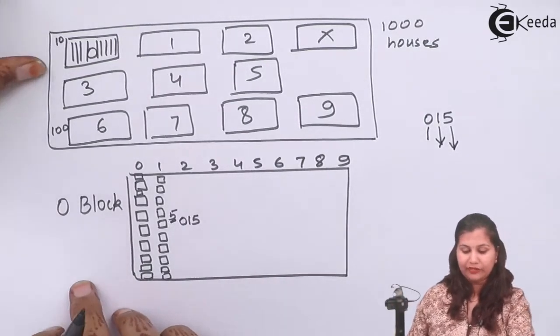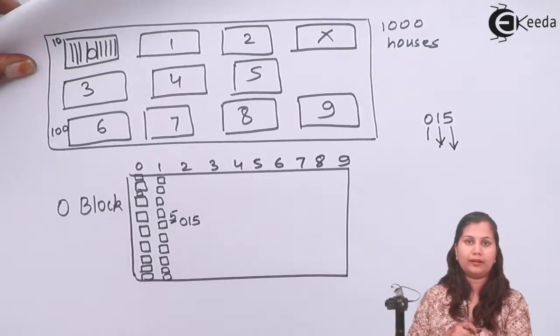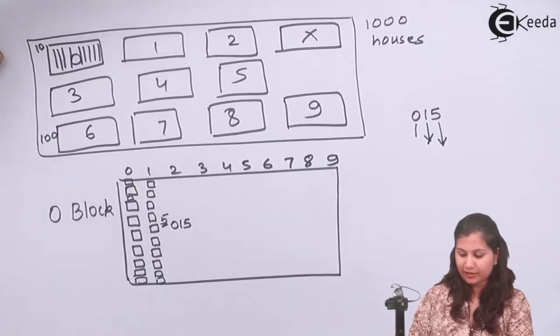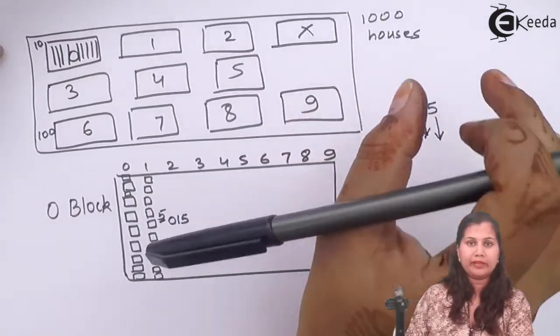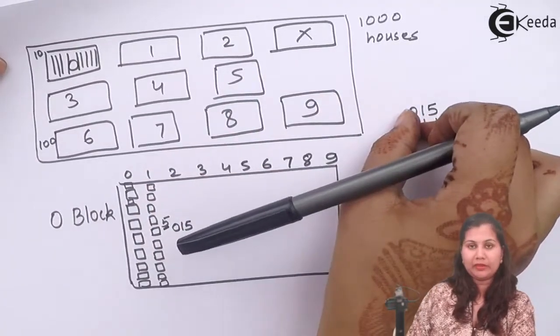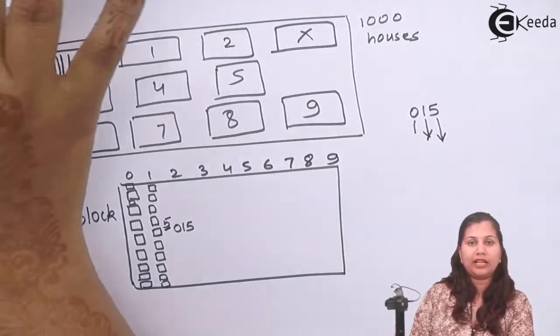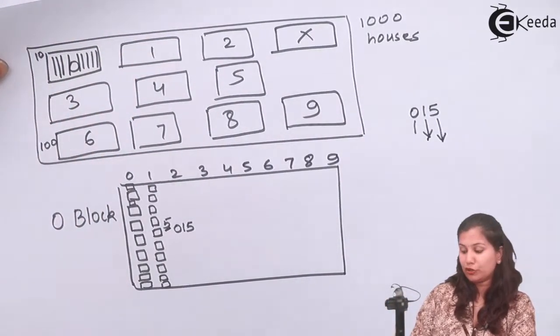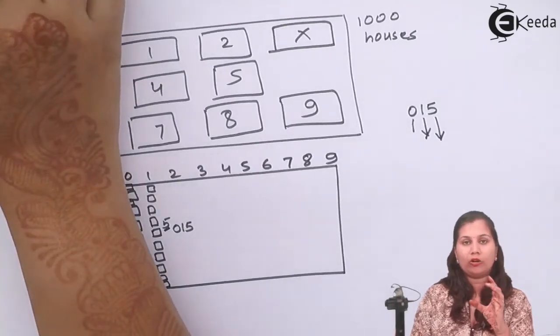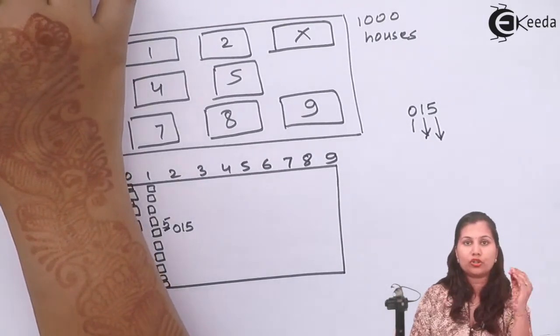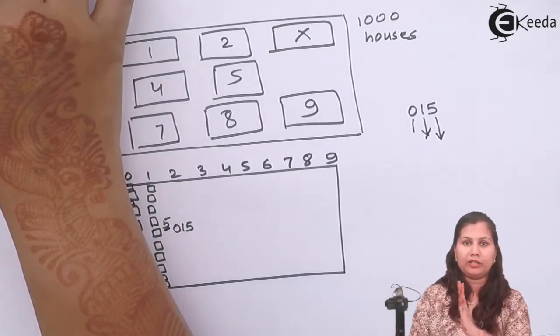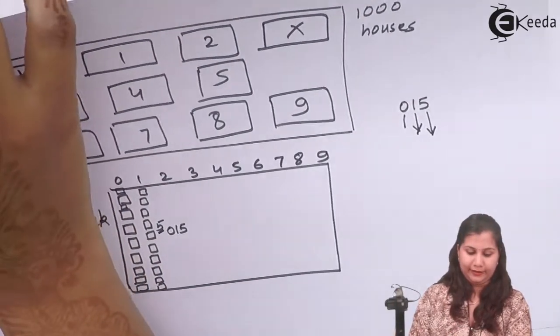A similar way is used to identify the memory registers and give them memory addresses. By this memory address, the microprocessor understands on which page it has to jump, and in that page, which row and which column number the memory location is located.